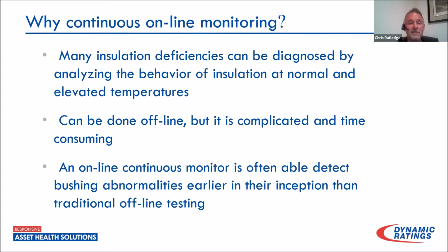I've seen a lot of instances where bushings were testing very well offline, and then customers would have them online and get their bushing monitor and say, hey, my bushing monitor is not working or is malfunctioning. And actually, no, it wasn't, but the problem had not reached a severe enough level to be detected with the offline testing yet at that point.